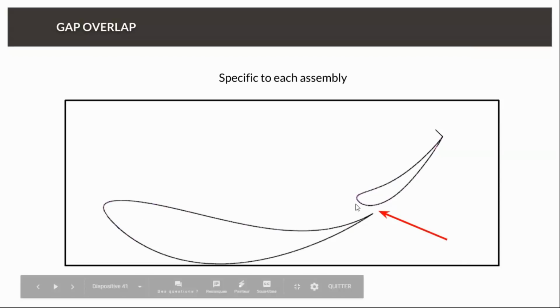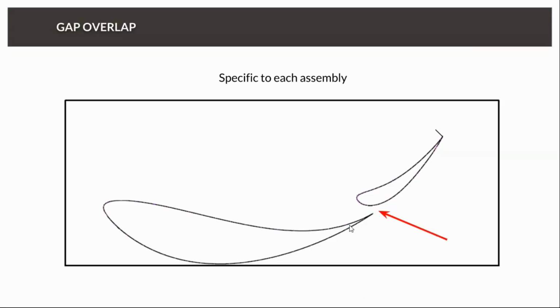racing car wings, where we will have a main plane, and when the rule allows multi-elements, we will initially start to load the main plane more and more, because drag-wise it's always an advantage to have fewer elements.